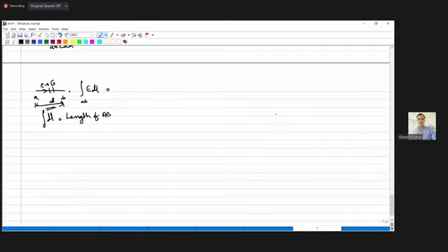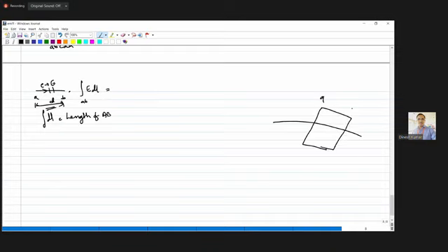Okay, see here, I am drawing here. This is the boundary. Here we are having the loop. So here we are having AB. This AB is completely present in the epsilon 2 medium. In epsilon 2 we are having E2. But the line AB is parallel with the boundary. So whatever the component of E2, we have to take the tangential component, that is called E2T. See here, E2T and AB are both in the same direction.